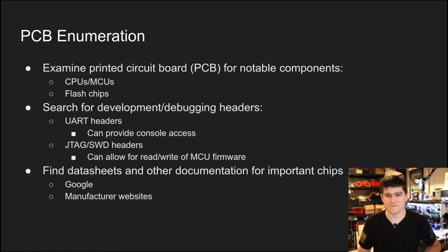Obviously, we're going to write that up as a finding if those interfaces are enabled, if those protocols are enabled. And then if we can get firmware off, then we're going to look for other vulnerabilities in the system from there. And then obviously at this point, we're going to do all sorts of open source intelligence. We're going to look for data sheets. Sometimes you can find those publicly. Sometimes you can find them in more gray areas out there on the internet. And sometimes they are completely locked away behind a paywall or an NDA or both.